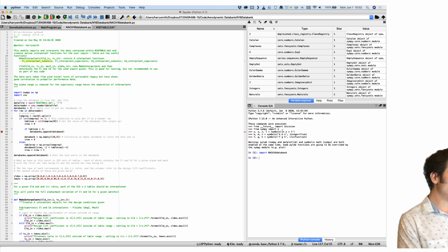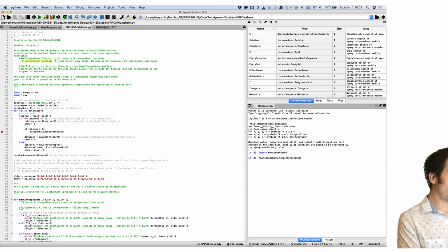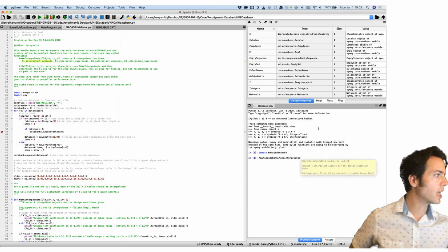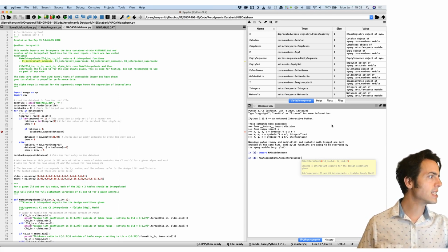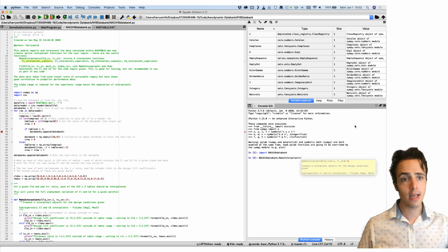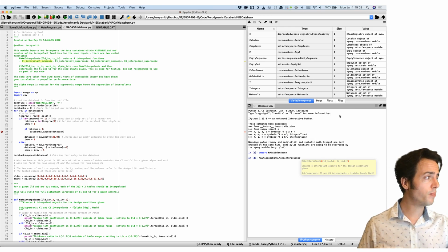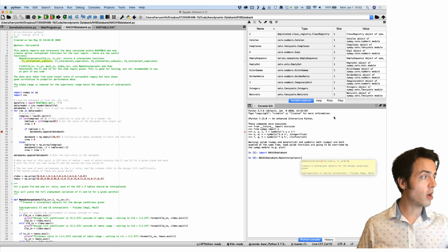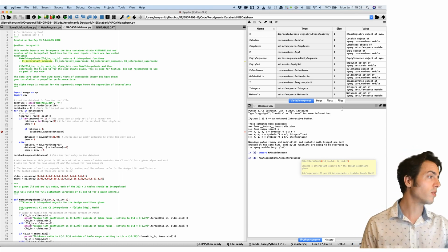Databank. If we want to say make interpolants, if we've forgotten what the syntax looks like, we can do NACA 16 Databank.make_interpolants. And as soon as I press the open bracket, it will tell me here. It gives 4 interpolant objects for the design conditions given. Subsonic and supersonic, CL and CD interpolants, which are a function of alpha and Mach number. And it asks you for 2 arguments, one of which is the design lift coefficient, one of which is the thickness to chord ratio. If you don't supply one of them, they default to 0.2.